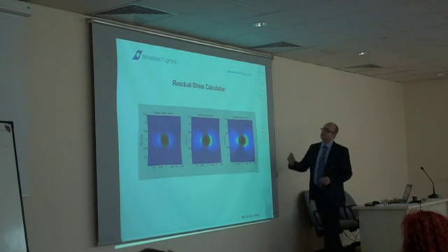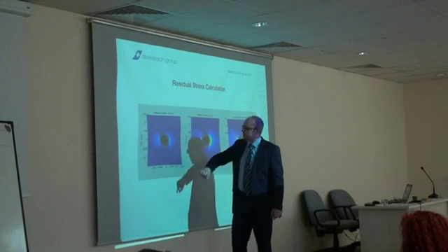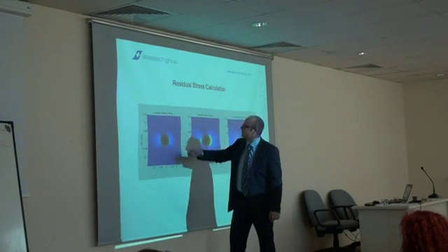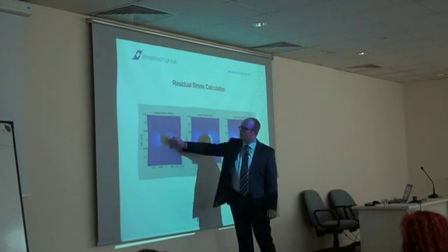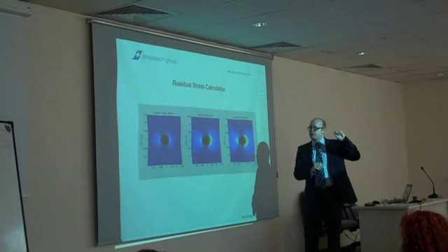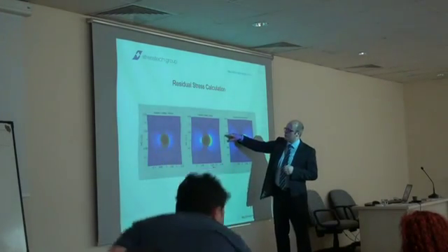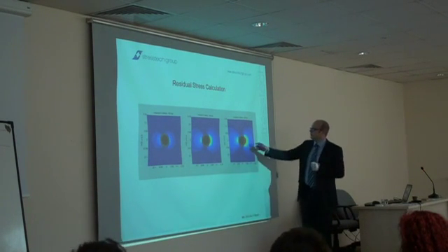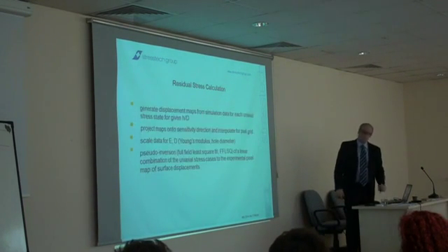And here is the same thing you can see in the maps. If you have just drilled, H per D is 0.2 and you have 100 MPa stresses, it's this kind of map because you are still quite close to the surface. You are not relaxing so much stress in the sample surface. And if you are deeper, with H per D at 0.6, you can see in the map that there is much more stress relaxed.